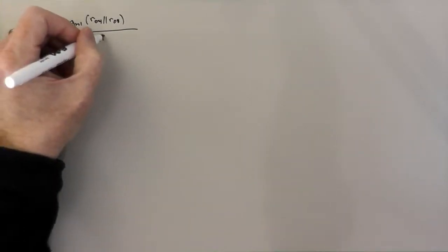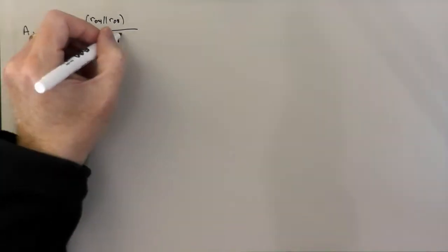Okay, in the last video segment, we were looking at the differential mode gain of our 9-transistor current mirror diff amp, and we found that ADM, with the load capacitance, was given by GM1 times RO4 parallel RO8, divided by 1 plus j omega times RO4 parallel RO8 times C out.